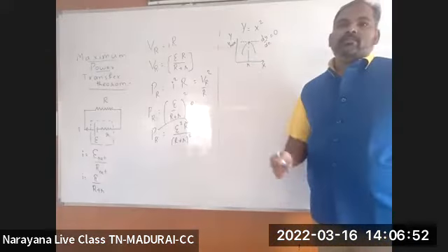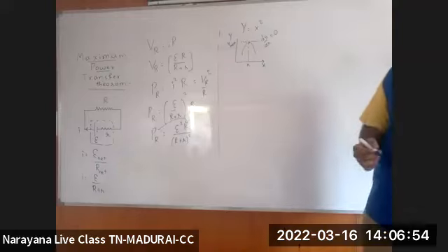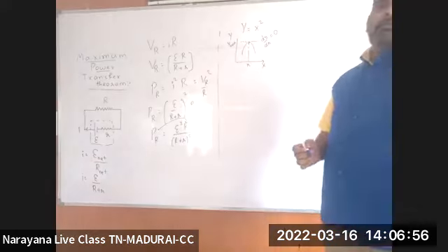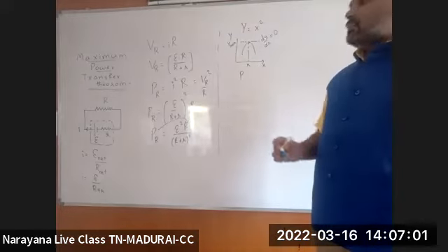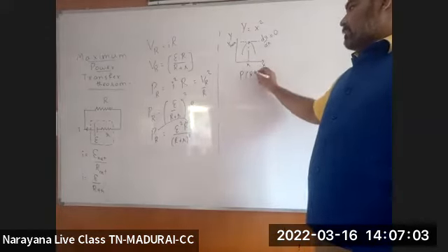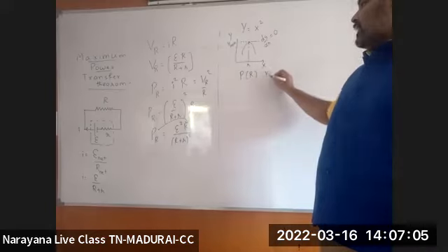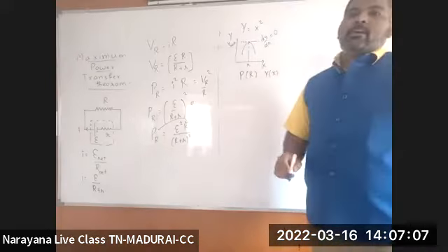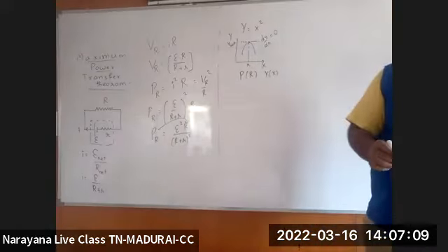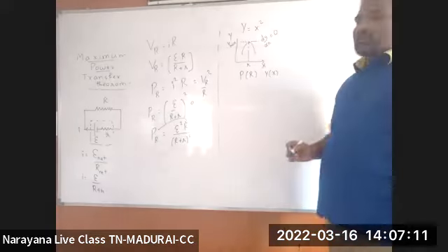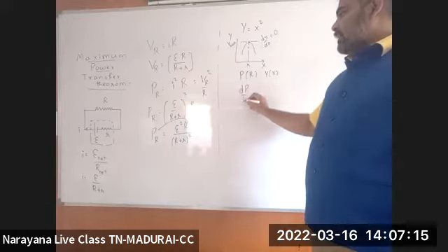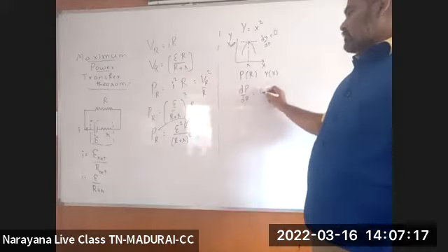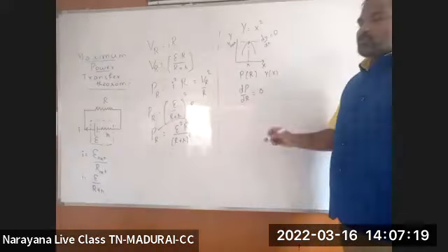So at a specific value of x here, the y value becomes maximum. The same concept I am going to apply here: the power dissipated by the resistance depends on capital R. How? Y depends on an x function. Similarly here, power also depends on the external resistance function. So when power is dissipated maximum, I can write dP by dR equal to how much here? 0.